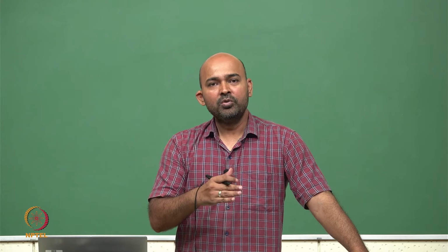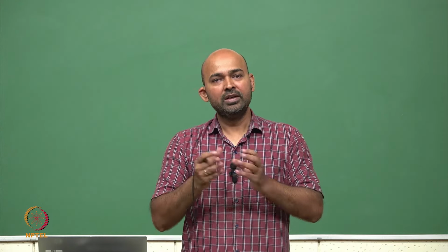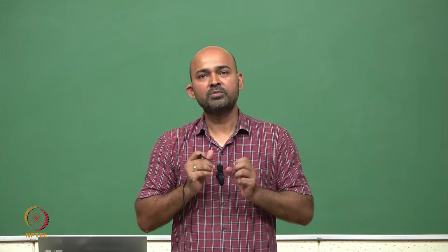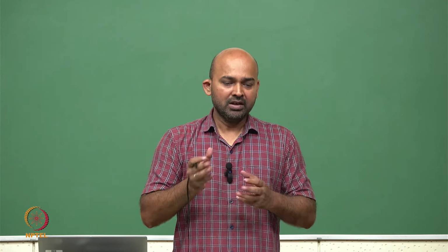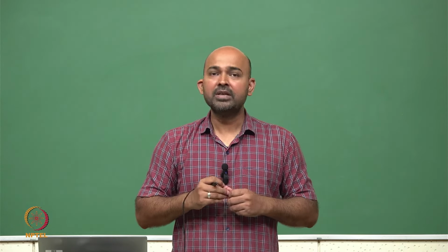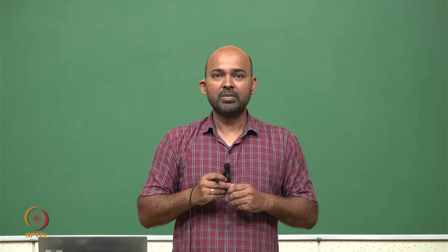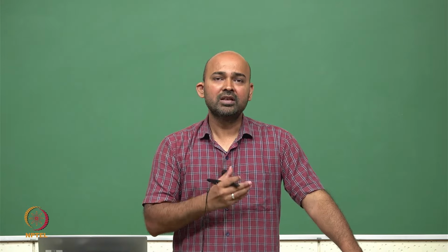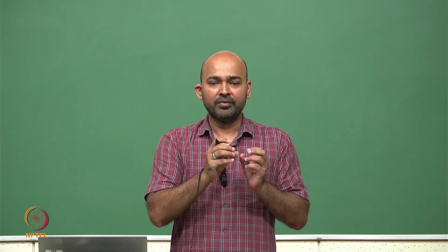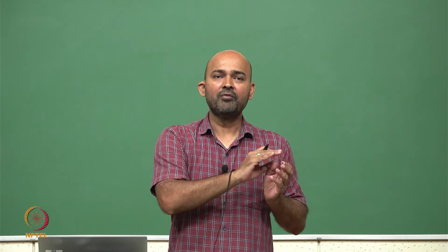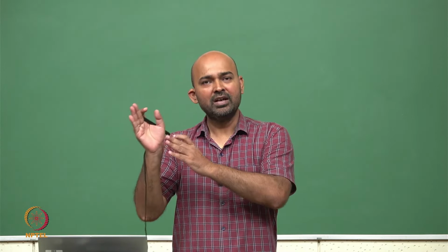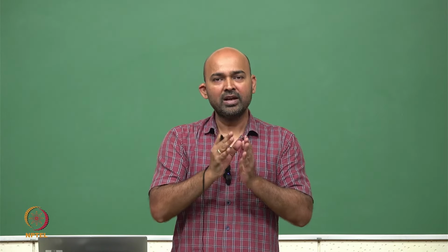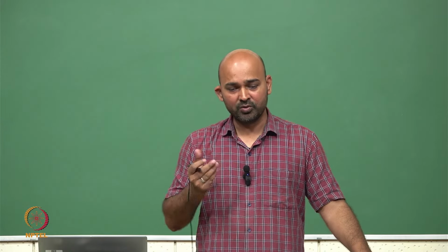However, when we want to perform certain types of analysis, we need to do DC simulations where we want to sweep a parameter and check how the circuit performs at different parameters. There we took the example of temperature. Temperature is a very general parameter which affects almost all electronic circuits. So, we are given a circuit, an active circuit or a passive circuit, and we want to sweep the temperature from a very low value, let us say minus 40 degrees, to a very high value, which is 125 degrees, and during this temperature change we want to analyze how the circuit is performing, how the output is changing.